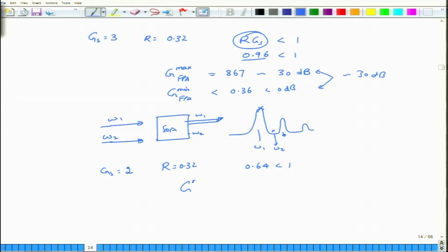that the maximum gain, again you have to verify that these numbers are correct, okay, please do that, the maximum gain is about 8.5 dB. The minimum gain is still quite less than 1, just about 0.32, but now you see that the gain ripple is down to just about 8 dB. So this is the ripple that you actually get, which is much smaller than this one.